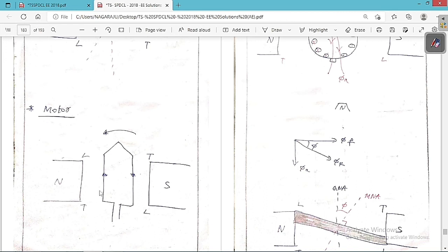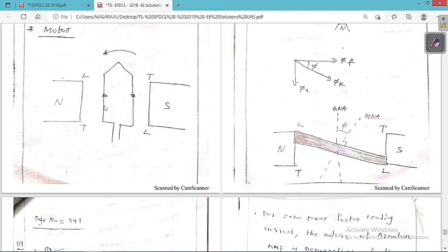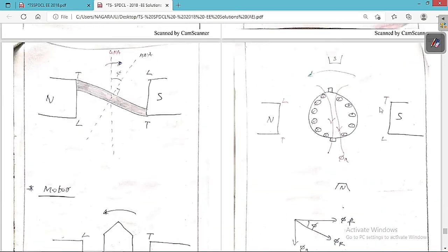So I cross B, the force is downward, electrical force downward. Here current is in this direction. So I cross B, I is here, B is here, so the torque is upward, force is upward. So this is going to rotate in the anti-clockwise direction. So I already told you, this will become leading, trailing, leading and trailing. This is the way I am going to draw the graphs. Whatever conductors are near the north pole will have current inward, means cross, and whatever conductors are near the south pole will have current in the outward direction, which is dot. Now we are going to see this one.